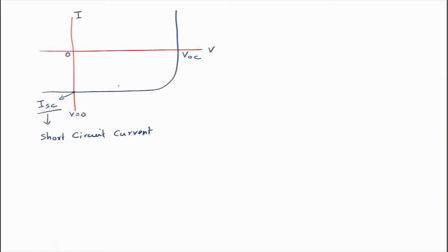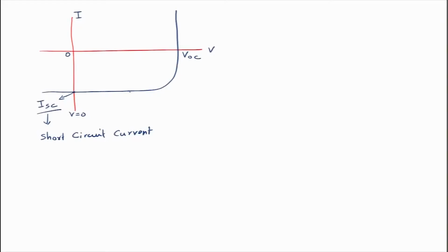Now this depends upon the type of solar cell that you have, the material quality, and what kind of recombination you have. For a perfect solar cell which does not have a high level of recombination, or a high level of SCR current or other kinds of currents, the ISC stays flat up to quite a bit of voltage, before it suddenly starts increasing. So for a dark solar cell you should obtain characteristics like these, and this shifts to the fourth quadrant when the solar cell is under illumination. So this would be under dark and this is under illumination.